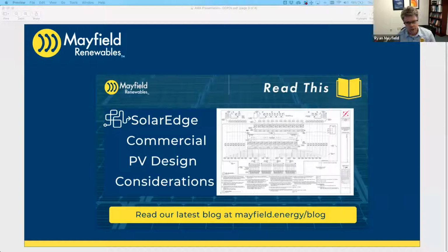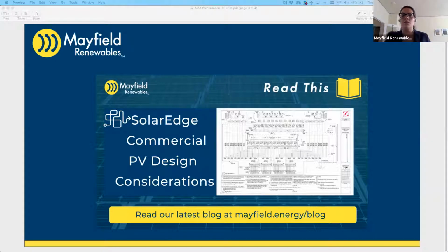So it's an interesting question that is definitely going to come into play more and more as we're seeing more and more bifacial. Yeah, and I know that a number of the racking and module manufacturers are starting to work together to produce additional data around this, because it is so important, especially with calculating performance gains for financial aspects. So definitely reach out to the racking manufacturer and the module manufacturers, because I know a number of them have that information, or are at least starting to collect it. So they might be able to help you out.